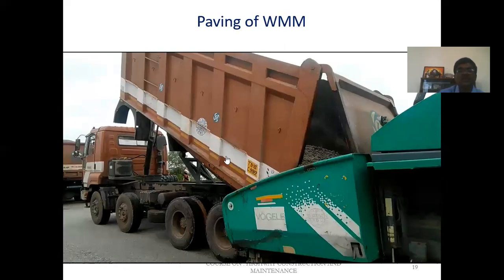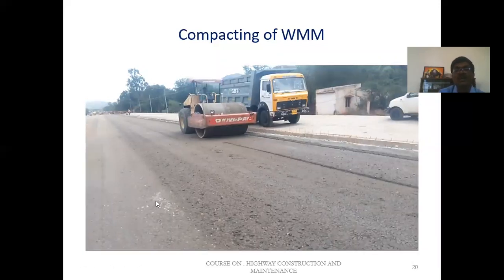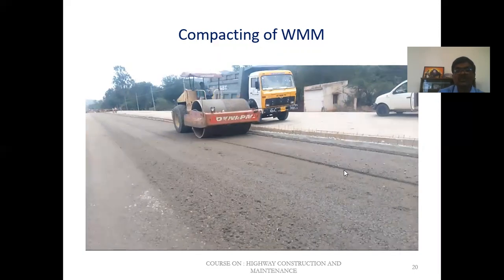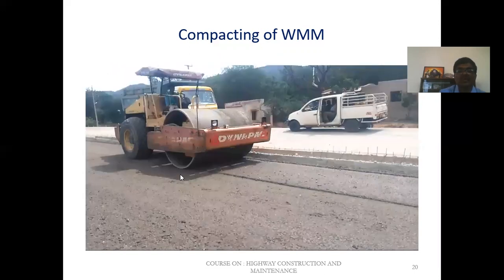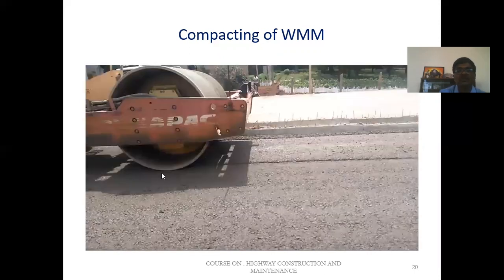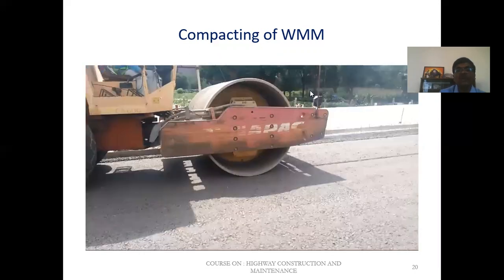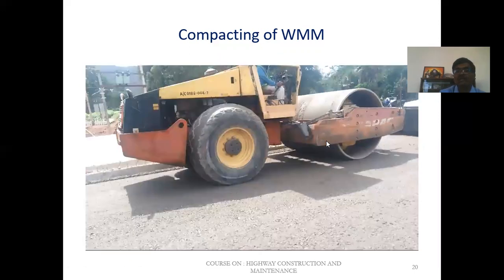So in this video, you can see the compaction of the wet mix macadam. You can see the paved wet mix macadam layer is compacted using an 8 to 10 ton class vibratory roller. This is a single drum vibratory roller.